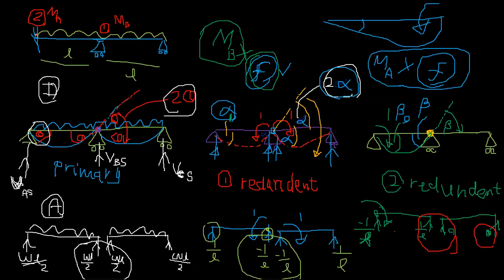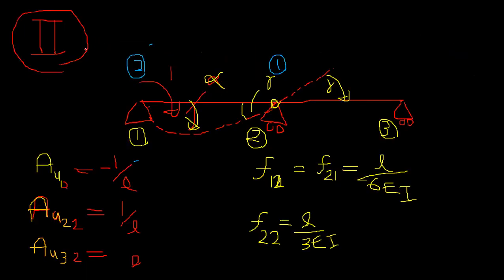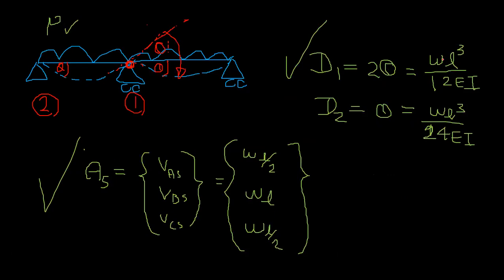Here in the force method, for your original structure, the first coordinate, the relative rotation is 0 because there is a continuous beam. So original displacement is 0. At A also, second coordinate is also 0. So the primary structure, you had WL squared over 24EI displacement, the shape, at the first and second.